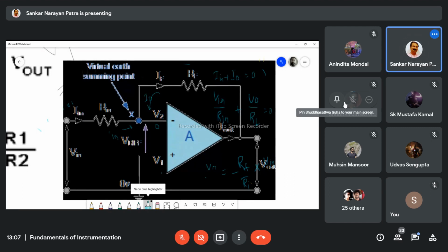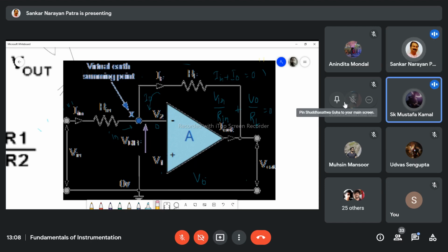No, I said V0 by Vin equal to minus RF by RI. Now I am writing V0. What is V0 then? V0 equals minus Vin by RI into RF.